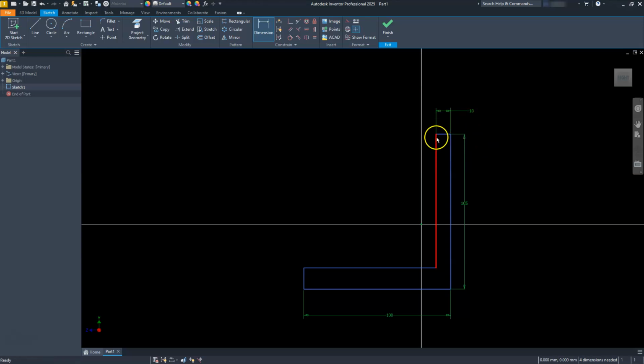Now in SolidWorks, you can make these two equal to each other, and it's the exact same principle here in Inventor. All I have to do is hit the equal button here, and then I'll select them like so. You remember in SolidWorks, we selected both of them, and then we looked at the options. We could have also hit the add relationship button up at the top. Now you can do the horizontal and vertical thing. In this program, I prefer to use the dimensions because it's a lot easier just to use reference dimensions, although I will use some of these constraints later.